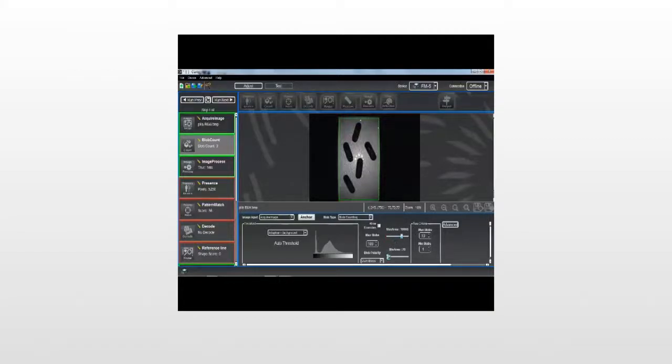Well, what I can do is use these sliders to set a region of interest for really the amount of area that the objects I'm looking for will cover in pixels. So really, how big are the objects I want to see? Well, you can see I move those up higher, and right away I recognize all these pills. And I'm recognizing from about 30,000 pixels to about 72,000 pixels of coverage for those objects. What I'm going to do is move this a little tighter. 46,000 I still recognize. Okay, 54,000, start to lose them. So let's move this up to somewhere in between there. 54, 51. And then I can move this down as tight as I wanted it to be for however discriminating I want to be for the size of those particular objects.